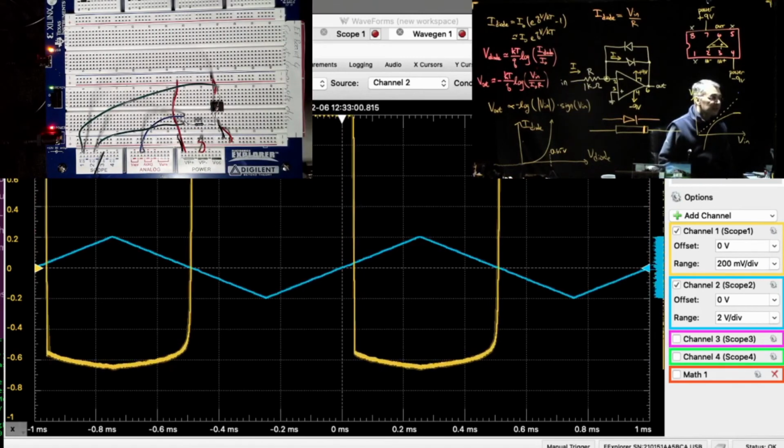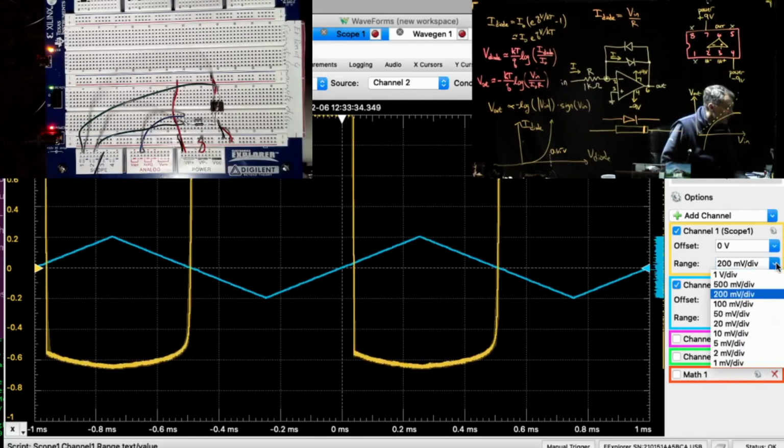I think it looks a little funny because the op-amp goes a little bit nuts, because the negative feedback path is broken once the voltage flips sign. So that's why we see something that looks a little bit funny down here. Actually, what's happening is when the output wants to be positive, there's no feedback anymore, so I think it just slams all the way to the limits of the power supply. In fact, here I'm kind of making this up as I go, but we could just take a look at that.